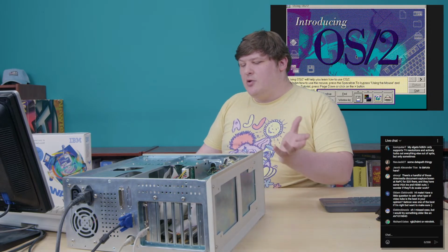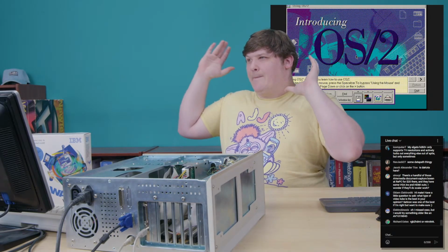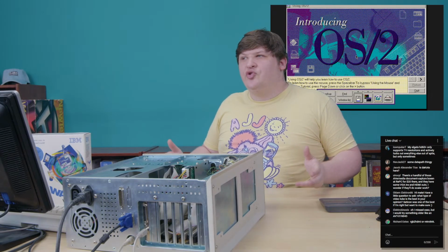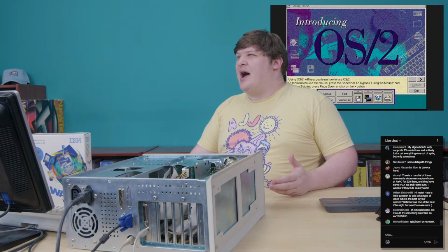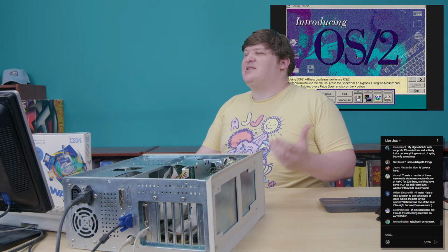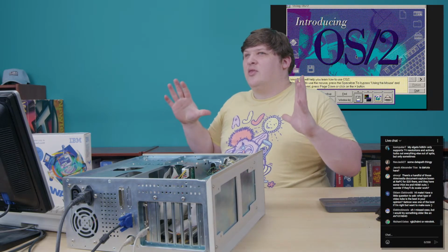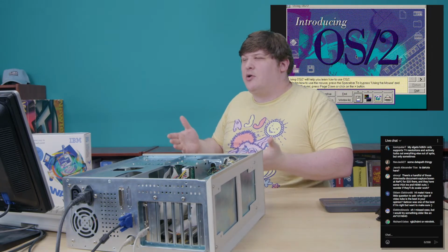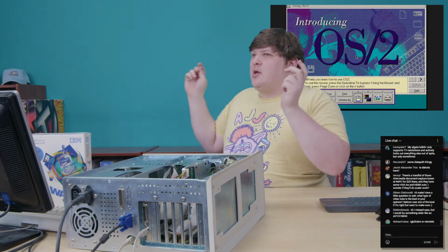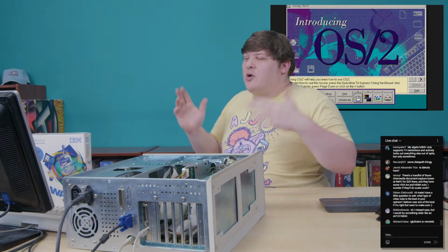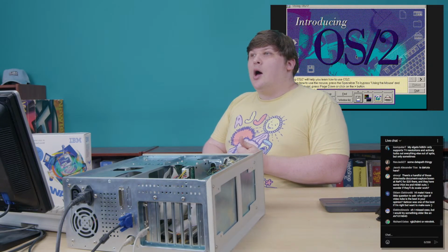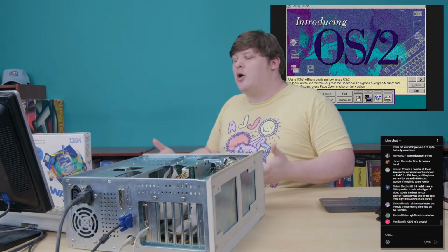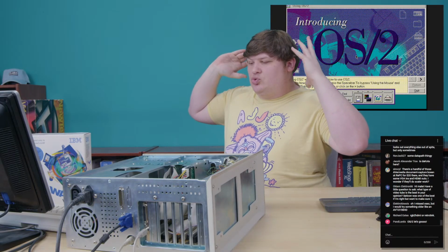Anyway, so this is just the universal hell of trying to do any of this sort of stuff. Because PCs in particular output a dozen different resolutions in the process of booting, right? You start out at 720 by some ungodly number at 70 hertz during text mode. And then the screen goes boom, boom, boom, and what the hell's happening in there? Who knows? And now we're back at 70 hertz text mode, or 75, or whatever it is. And then the boot splash for your OS starts, and is that a VESA mode? Is that a VGA mode? And then boom, boom, boom, and then you load into the operating system, and now it's a new mode. And so you really can't set it and forget it.